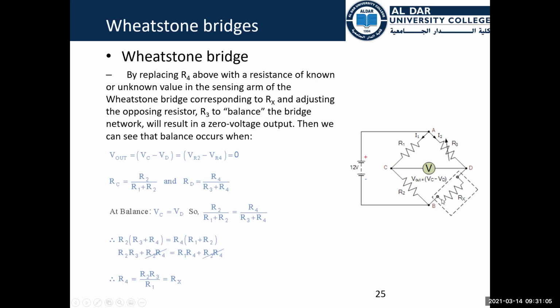Why do we want to calculate Rx? If we want to balance this Wheatstone bridge. Balancing it means to get the output voltage to be zero. I want it to be zero. What to do? Just change Rx to the amount that I need.